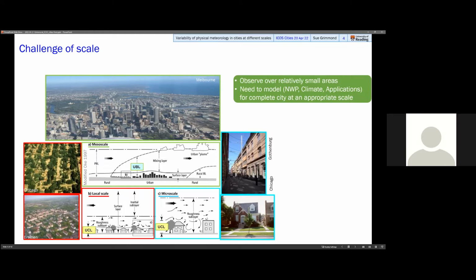In the central business district, we see a whole series of tall buildings, but it's not actually very extensive relative to the height of these buildings. The depth of the roughness sublayer, so the boundary between the roughness sublayer and the inertial sublayer, is typically assumed to be about 2 to 5 times the mean building height. And this depends on the packing density of the buildings.